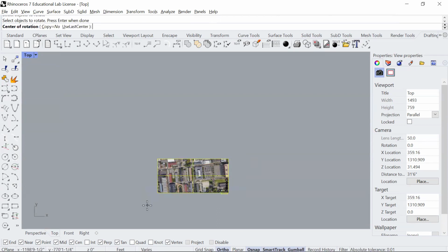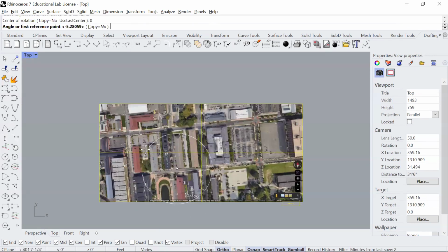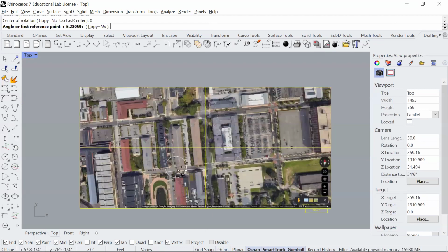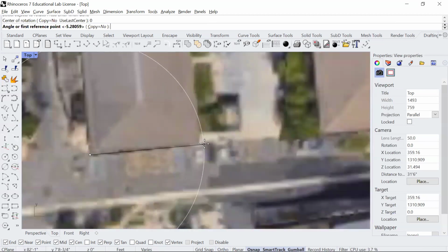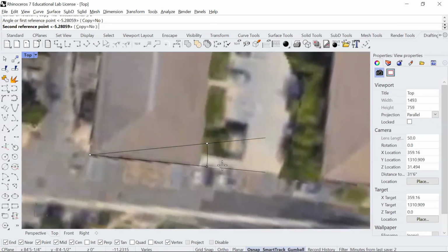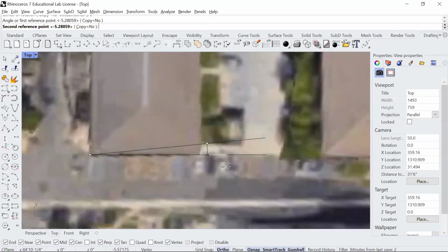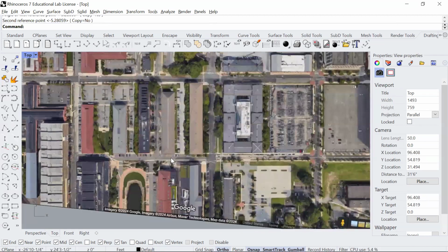I'm going to say enter, press 0 to go to the same origin point. This allows me to rotate. Now it is on ortho, so we don't want that. Click the ortho out, and we're going to do just as best as we can that angle of the building. Click once, and then take it to the ortho. You can do shift, or you can press ortho again, whatever is best for you. If you click that, that sounds good.